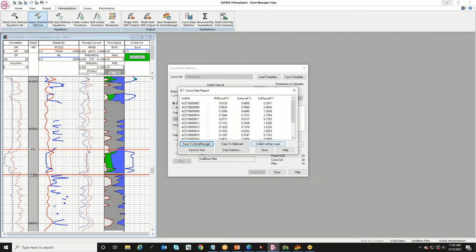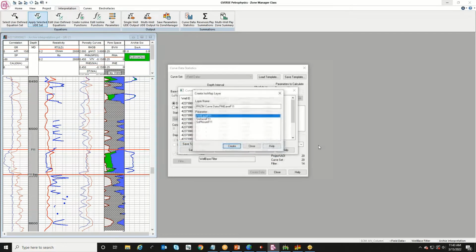Like I said, your other option is you can go directly to creating the isomap layer. Same kind of thing, you just choose which parameter you're building, give the layer a name, and you'll go through and build out some of the grid information. Smallest feature radius, are you going to be using a boundary polygon? Are we changing any of the contour interval information? Are we plugging in any color fill into that? Similar options you see whenever you create an isomap layer.